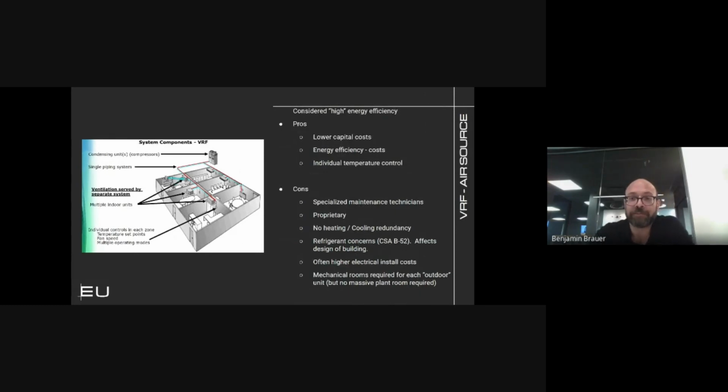The last mechanical system we're going to discuss is the variable refrigerant flow, or VRF, systems. VRF is a proprietary term actually reserved for Mitsubishi VRF systems, or multi-split units. VRV is commonly used for Daikin, LG, Samsung, and others. But the family of mechanical systems, let's call it, is most commonly referred to as VRF. VRF is the family of mechanical heat pump systems that utilize one outdoor unit for several indoor units, or multi-split systems. VRF systems are 100% refrigeration, not to be confused with water systems.